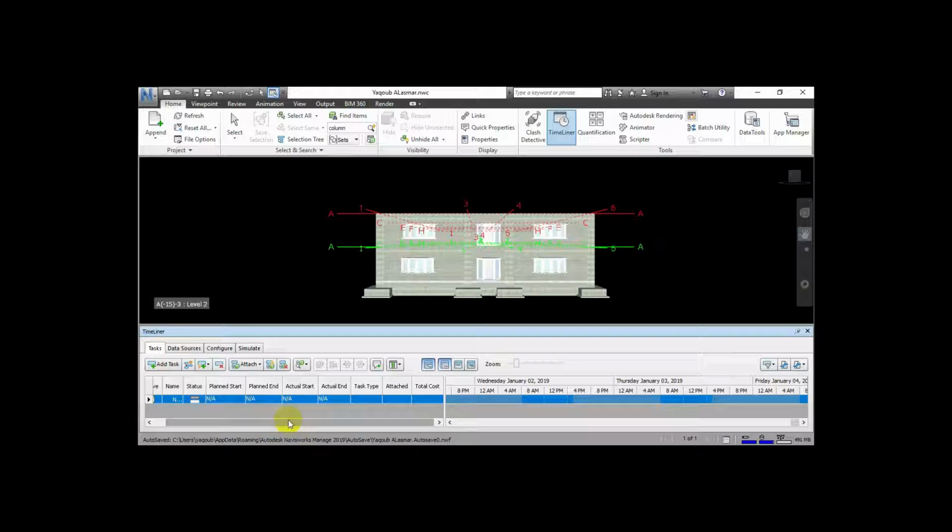Before we start adding any task, we should have in the beginning the activity names, and we should have the planned start date and the planned end date, and we should have the type of the construction. To do this, you can do it by Excel manually, or you can do it by Primavera. Assign the duration and the name of the activity and the relationship between the activities in Primavera, and Primavera will give the output by the start day and the end day.